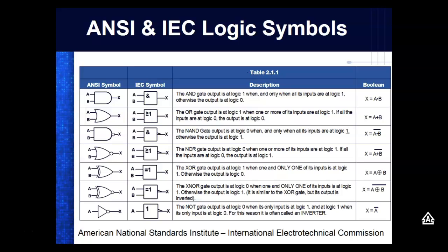So at the top that's an AND, then we have an OR. Then we have a NAND, so notice on a low active output, this is a triangle. Now this is an OR. It's got the same symbol as the OR, but it's got the little low active symbol. This is an exclusive OR. This is an exclusive NOR. Here's the output, they're equal, the output is low, and this right here is a NOT. So in PLCs, if you program using a logic block diagram, then these are the symbols you'd have to learn. But the Boolean algebra would be the same.